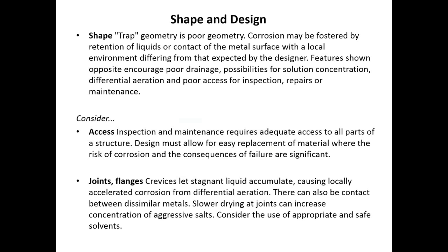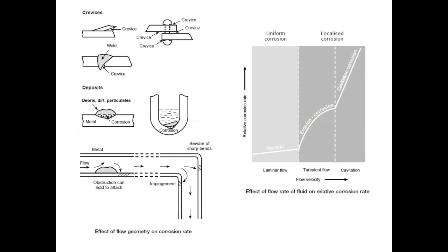So I could refer to this diagram, which shows that crevices, or areas where you have local cell concentration, which people call crevice corrosion, are areas where very little flow is occurring, or you can have a higher concentration of the corrodant in that area. Hence, it is an area that necessitates closer scrutiny for inspection, and at the same time, it's almost predictable that more corrosion occurs in that geometry, or with any particle debris or deposit that adheres to a surface.